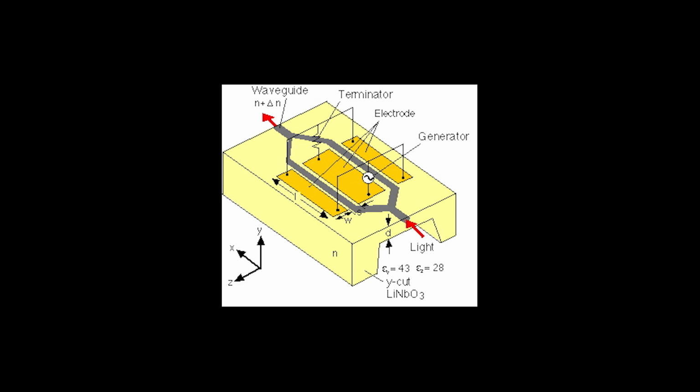Instead of changing the physical distance between optical elements, Mach-Zehnder interferometers in optical communication control the modulation by utilizing an electro-optical crystal. By changing the voltage applied to the crystal, the refractive index of the crystal changes, which in turn slows down the light in the crystal and introduces a phase shift into one of the arms. When recombining the paths, the phase modulation gets converted to intensity modulation. Essentially, by feeding the crystal modulated voltage pulses, pulses of light are a result.